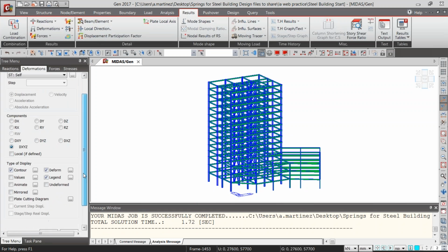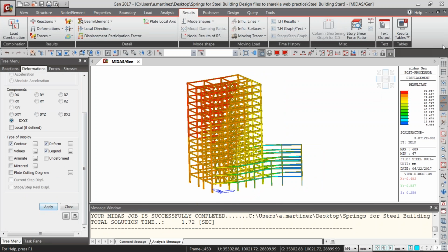So under the same load case, now with soil springs instead of a fixed boundary, we see a much larger displacement. In this case it's actually considered settlement as well, since it's not just the structure being deformed, but it's also sinking since we're modeling the soil as a spring. So we see this completely new distribution under soil spring conditions instead of the fixed boundary.